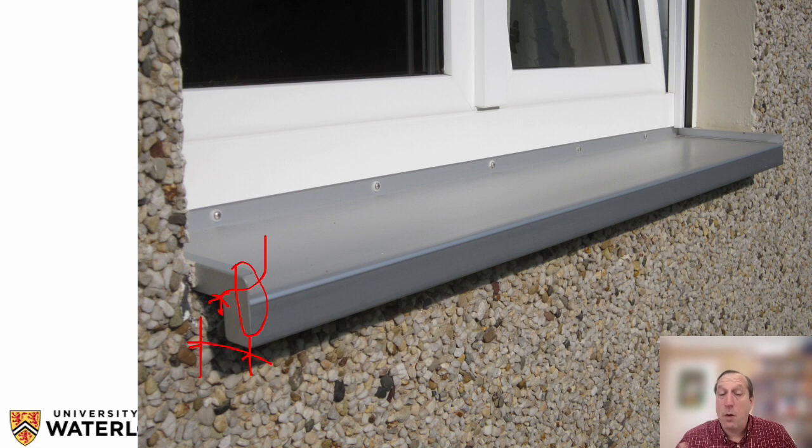Often missed, and it's actually challenging because right here at this corner is where a lot of water will be pushed by, say, the blowing wind. It'll either be this side or it'll be this side. And so here they have this upturn, side or back dam, end dam, sorry. This is a back dam right here. This is at the back, and that makes sure that the water flows this way. This is an end of the sill or side of the sill, and that makes sure the water flows this way.